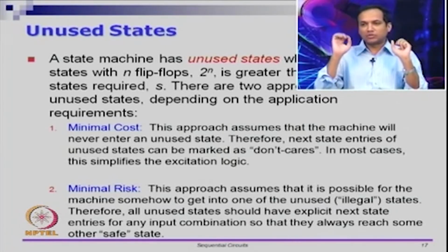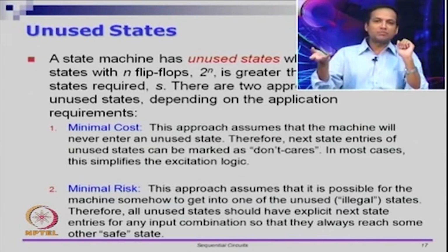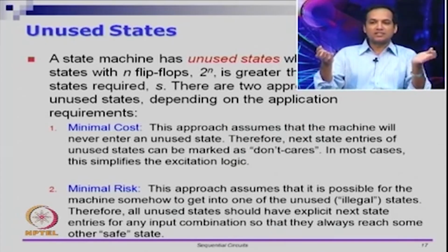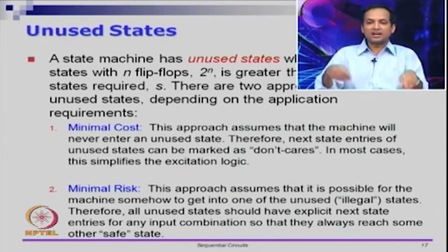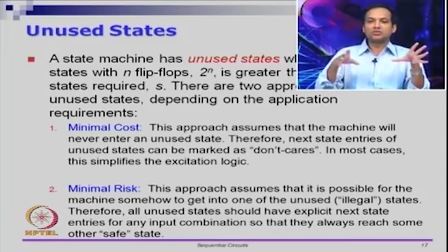Minimal cost and minimal risk, both of them have issues, but the primary reason why something like this can happen is that when you power up the circuit, for instance, you may not know what the values of the flip flops are. You should not assume that when I turn on a chip, automatically all the flip flops will be zeros or will be ones and so on. We cannot assume that. The flip flops may start in any state, unless you put an explicit reset so that you bring all the states to some known condition. This may be a problem. So typically, as a good design philosophy, you have an explicit reset state so that you power on the machine, you do a reset so that all the flip flops start with some known values. If you do not do that, it is possible that you can start the circuit in an unused state.